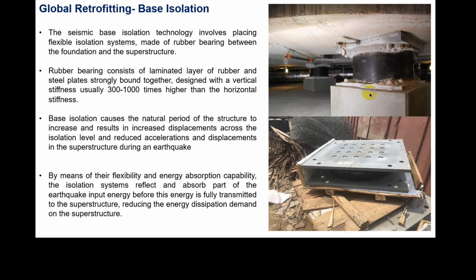It means they are very good energy dissipating devices, and with the help of the hysteresis loop on the cyclic load that occurs during the earthquake, they have a good broad hysteresis loop. And in the analytical case, the area of the hysteresis loop in its cycle is the amount of energy dissipated by this device or absorbed by this type of device.